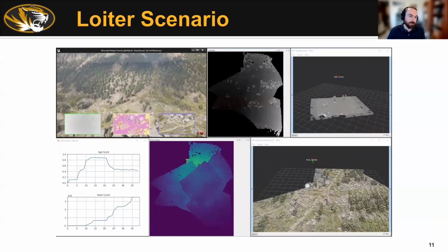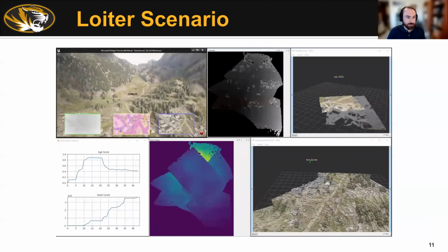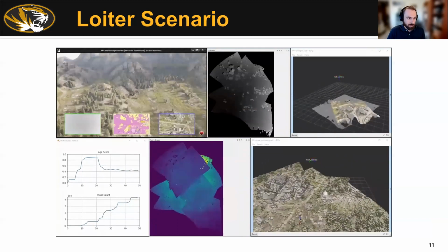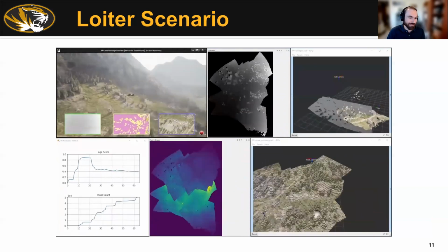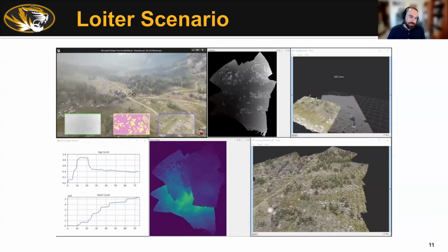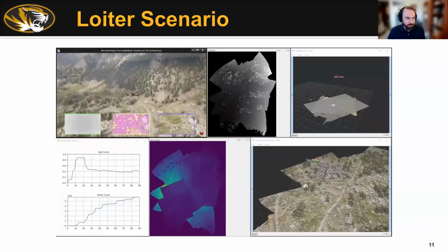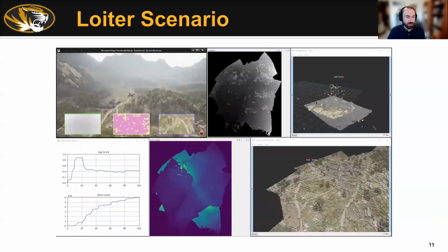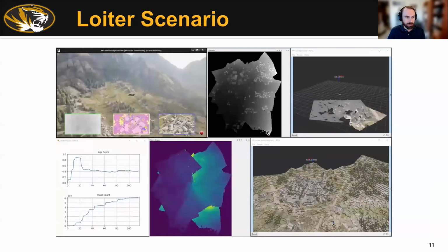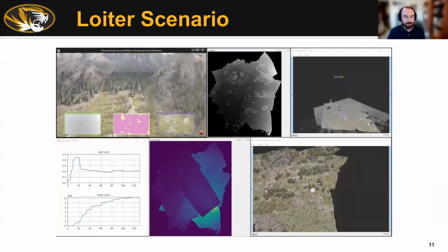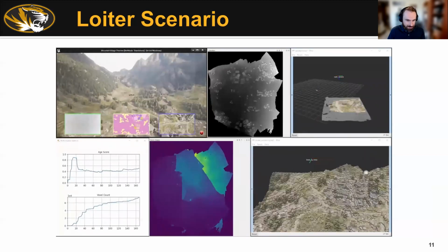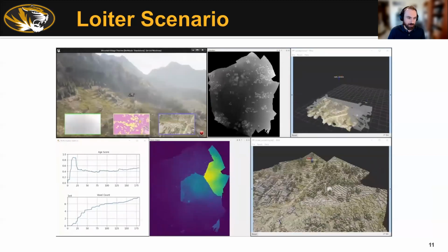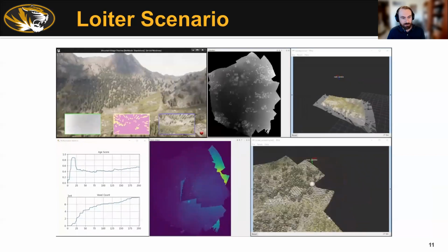In the top middle, you have the elevation profile, and you can see now it's being sped up so that we don't have to wait for this whole thing to take place. But it's exploring where it wants to go. Down in the bottom middle, you see the combined score features, and that's being used to decide where the drone should go. The bottom right shows our voxel grid, where that little white sphere represents the current target location where it thinks it should be going next.